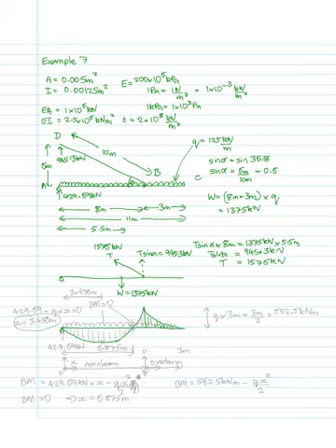So let's stick the reaction up there, 429.69 kilonewtons. And then obviously on the beam right there we're going to have a UDL, and then we would expect a bending moment distribution like there, and then that point is the point of zero moment.